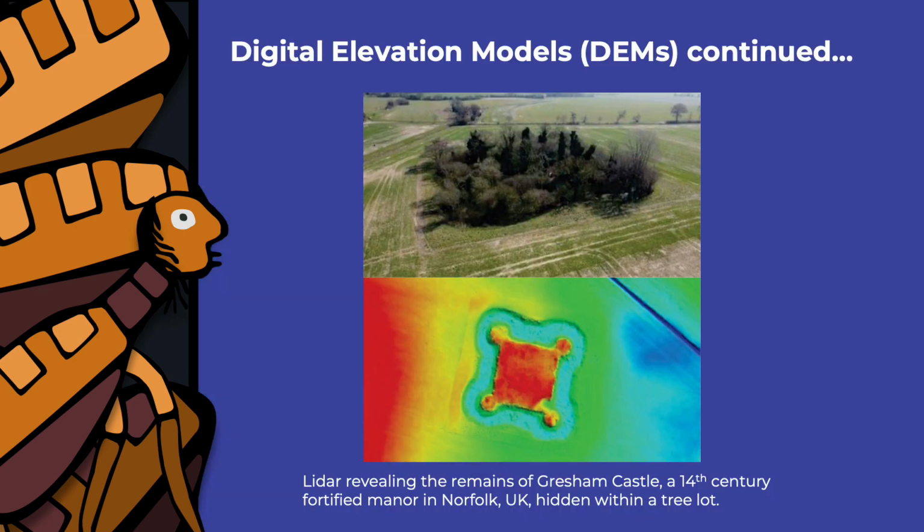The second method for creating a DEM is LiDAR survey, which uses lasers to obtain very accurate distance measurements. LiDAR systems send laser pulses downwards to measure distance to the ground. The sensor measures the time taken for millions of points of laser light to leave the UAV, strike the surface below, and then return. This three-dimensional information forms dense point clouds that precisely define the surface. LiDAR survey also has the advantage of being able to survey through wooded areas to obtain DEMs on the ground surface below the tree canopy.